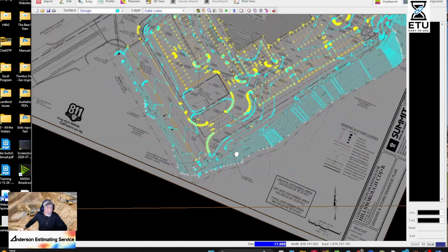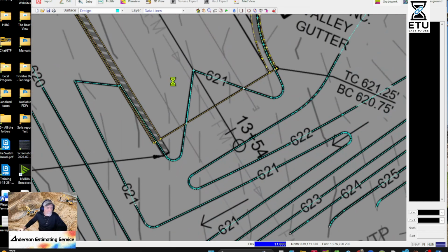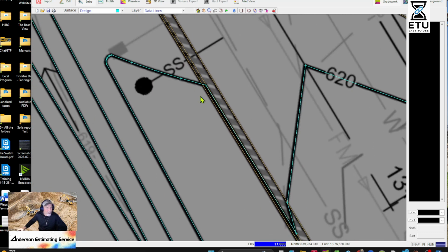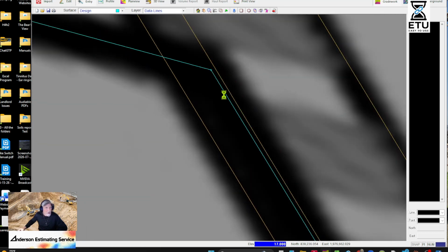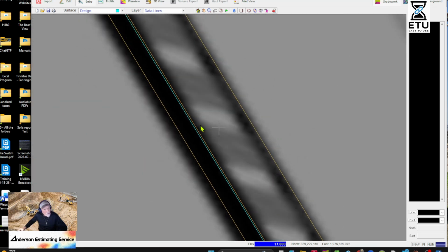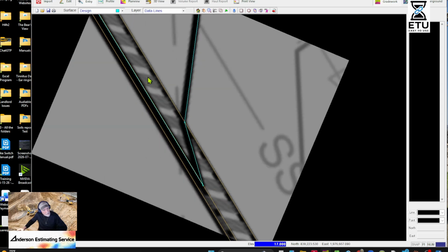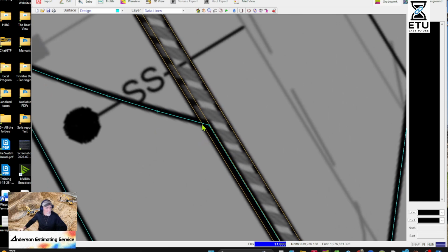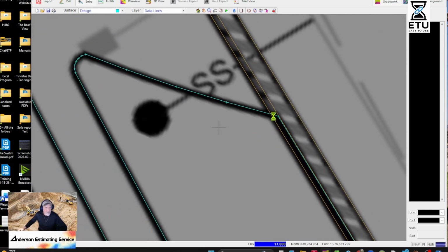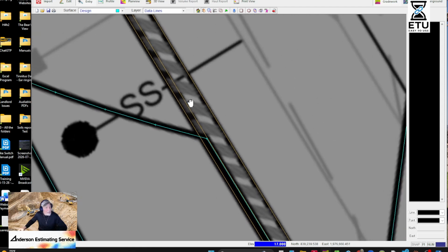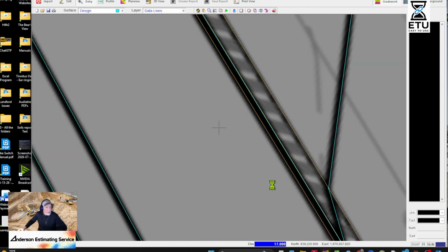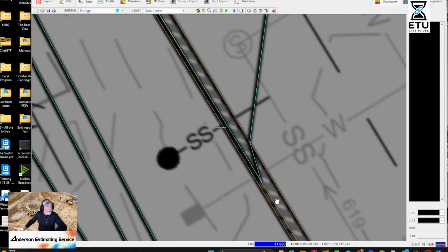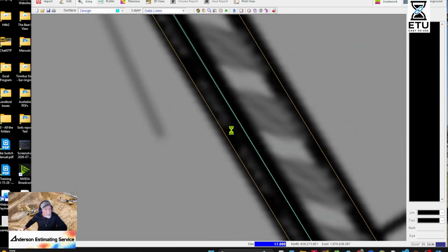Now, let's go line up. Let me show you how we can do this fast. I see a problem here with these. See how these contours are running straight along? This should run from this point to there. That contour is wrong. So what you can do is trim these all. We're not going to do that today because that takes a long time, but I would trim these if they get too close, see?